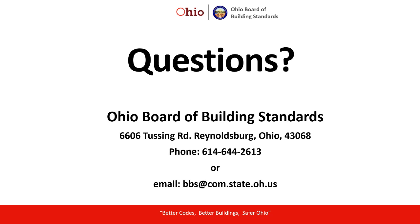On the tiny homes, typically what you'll run into is, because the overall square footage of the house is small, you're going to see issues with minimum rise and run requirements on stairs. You may have ceiling height issues getting up to a sleeping loft. Because you have a sleeping area, you're going to have an emergency escape and rescue opening, and there's minimum sizes for that. You may have to define what those are.